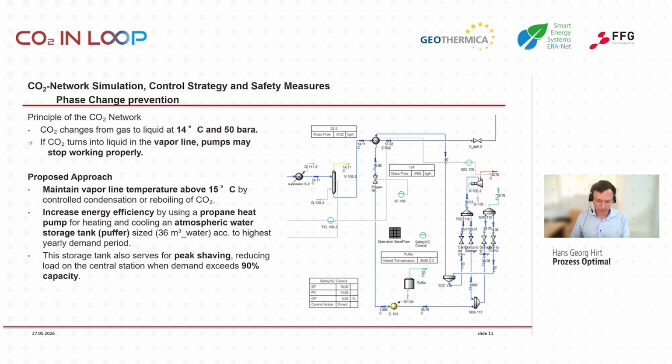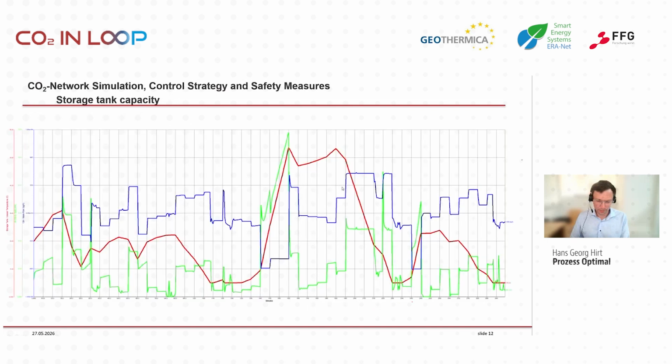And because it's a research project, we also wanted to be as energy efficient as possible. So we are just storing the energy in this buffer we need for this temperature switches, and we are just trying to gain the energy by another heat pump. We also tried to size this buffer vessel according to the highest demand in the year. So we have enough energy reserved to keep this buffer in operation.